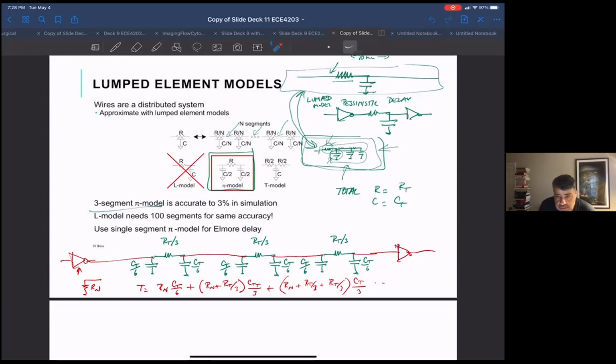If you don't do that, you're toast. The thing that tends to throw off your matching are the parasitic capacitances of your layout. You're always trying to match the shapes of your interconnect to replicate these parasitic capacitances and crosstalk and all that.